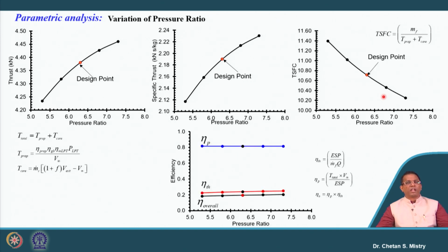Let's correlate that in terms of efficiency. Here if we look, it says with the increase of pressure ratio, our thermal efficiency will be increasing. Yes, as we have discussed, that's correlated with the power. And what is my heat input? My heat input will remain the same for all the cases because it's m_f into CV.